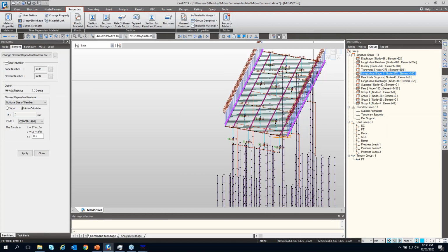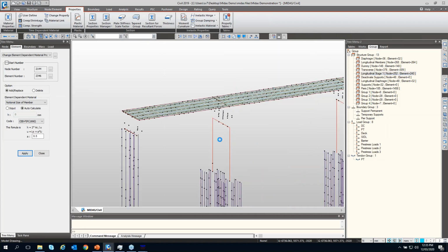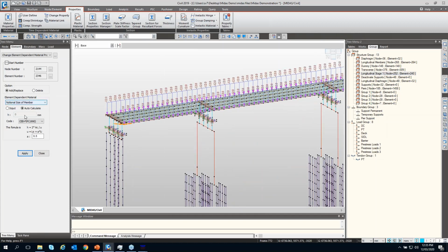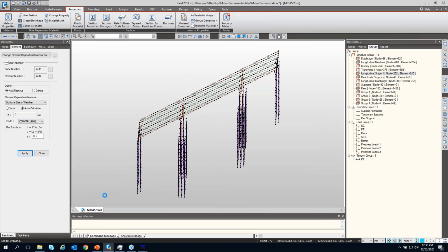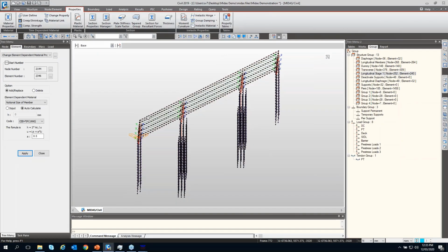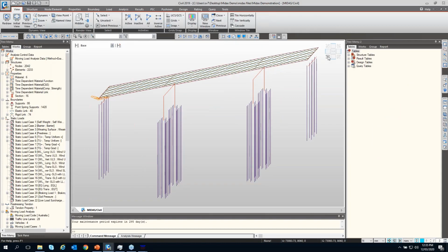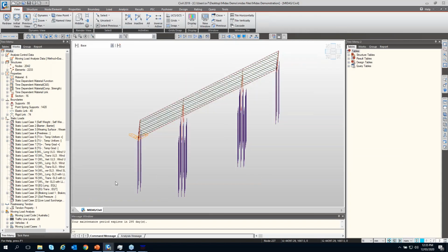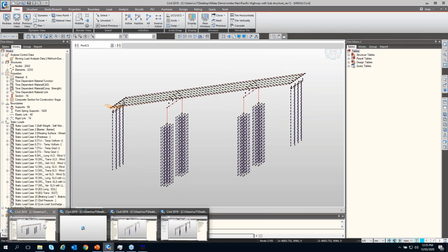So you can select the longitudinal elements and apply. It'll basically apply the section hypothetical thickness based on the calculation here, which is 2 times area by the perimeter which is in contact with the surface. So let's get to the analyze model just to see the results.